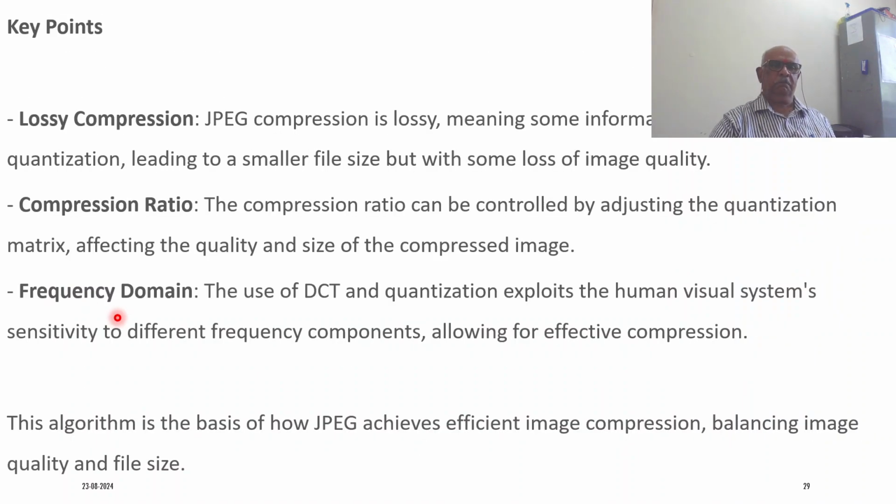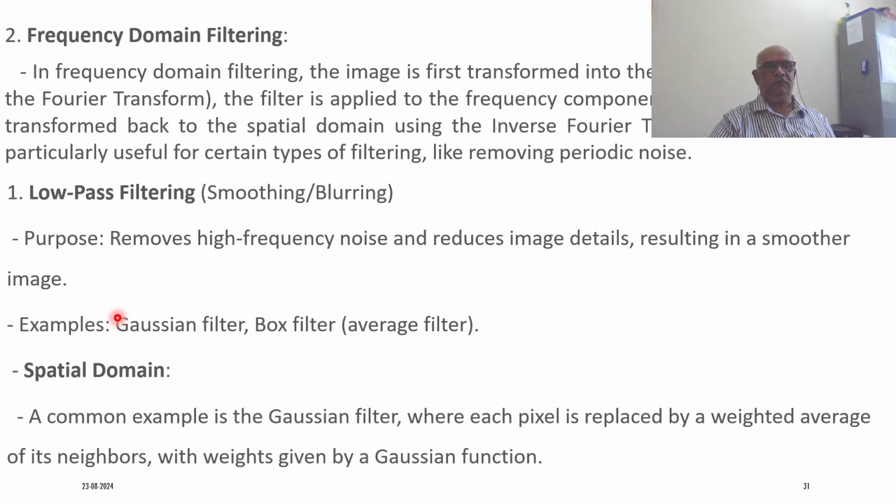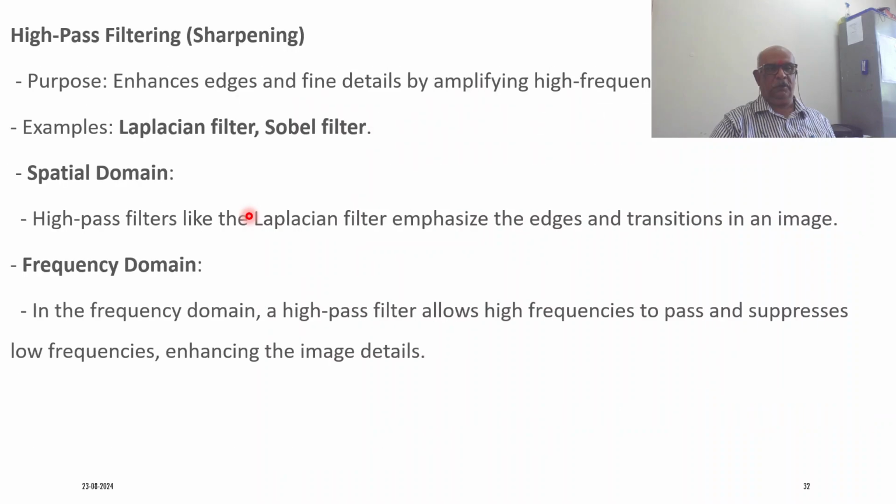So essentially, we also do the filtering, that is a kind of low pass filtering, wherein you try to smoothen, you want to blur it. So in case you have got any steep change, any abrupt change, as we have seen, it's a high frequency component.